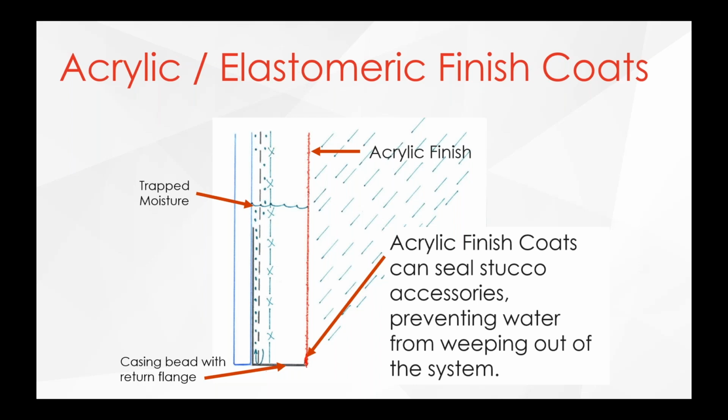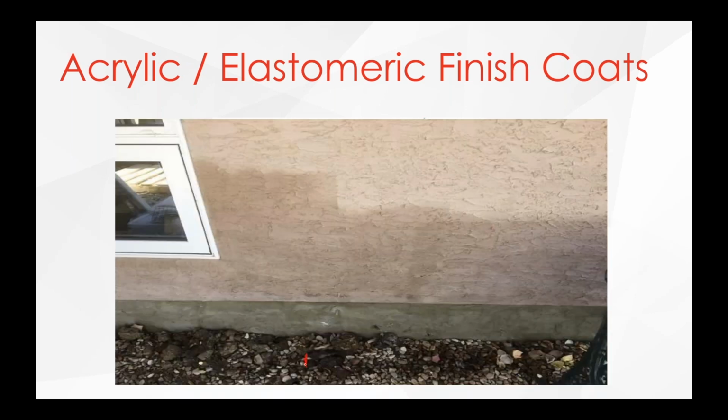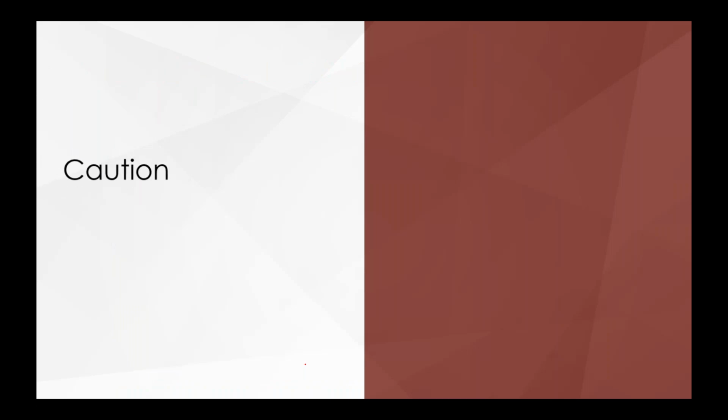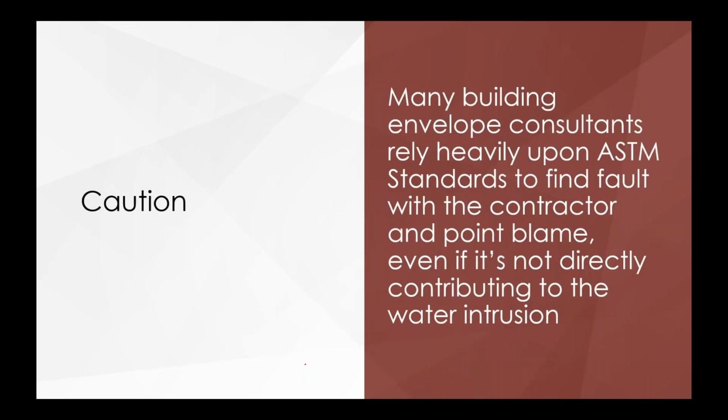If you've got a weep, you always want to have a sloped edge there. Again, this is what it might look like. And I know those who know stucco will say that's not an acrylic finish. I realize that. I'm just showing the image of what happens sometimes when you've got too much water in there and you have that staining. It's because the exit doors are blocked, basically. All right, so picture this now.